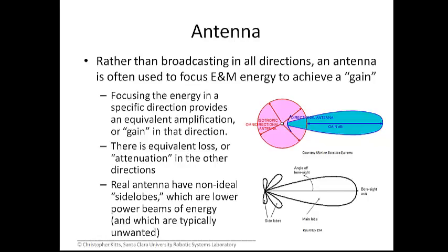The power does taper off in other directions, but sometimes you have little focus concentration areas called side lobes, which you need to pay attention to because you are broadcasting with some level of energy in those specific directions. And so that might be an interference source to somebody else, and you think you're pointing one direction and somebody in a different direction is hearing your broadcast because they're basically captured in a side lobe.